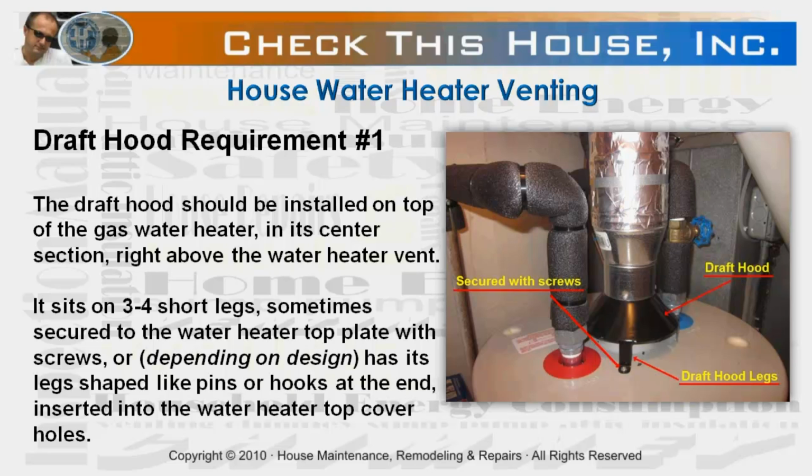There are three basic draft hood requirements. Number one, the draft hood must be installed on top of the gas water heater in its center section, right above the water heater vent. You can see on the picture that the draft hood sits on three, sometimes four, short legs, which are either secured to the water heater top plate with screws, or, depending on the design of your appliance, have legs shaped like pins or hooks at the end, which are inserted into the water heater top cover holes.